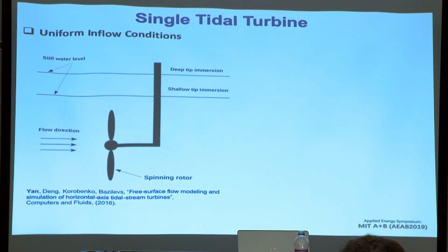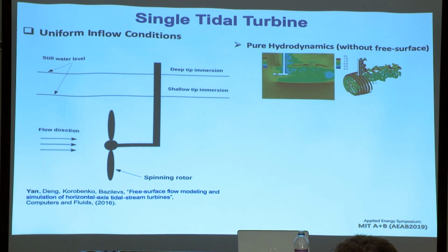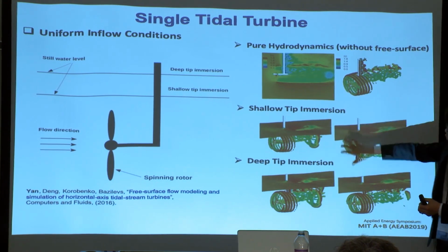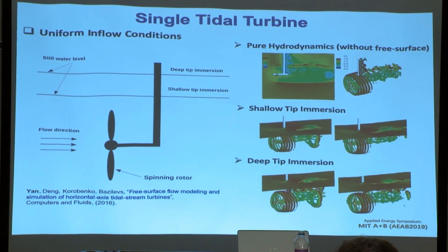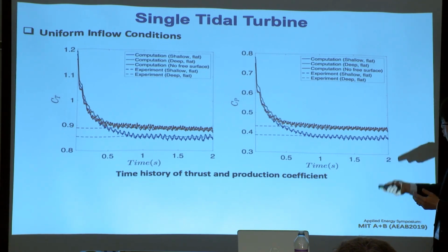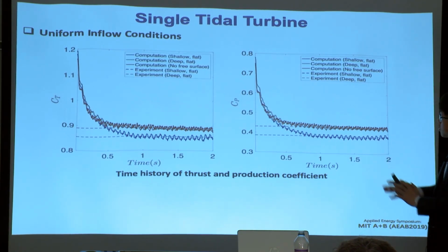We investigate the effect by first using a uniform inflow condition. We performed pure hydrodynamic simulation without free surface effect, and we also computed free surface simulation. We also did free surface simulation with 2 different immersion depths. Those immersion depths are from the experiment I showed you before. So these are the most important results. Those 2 figures show you the thrust coefficient and the power coefficient for all the simulations.